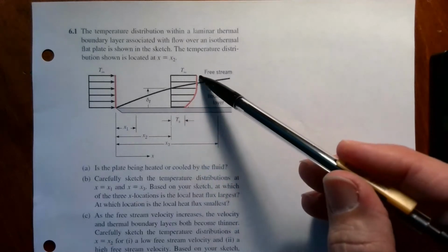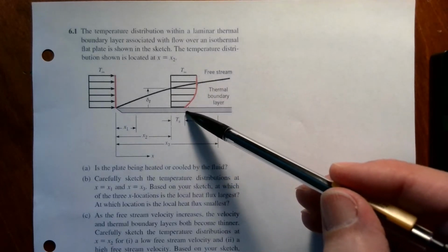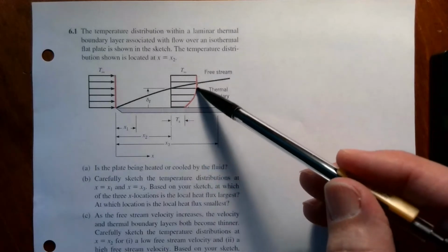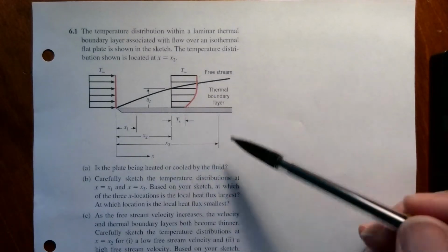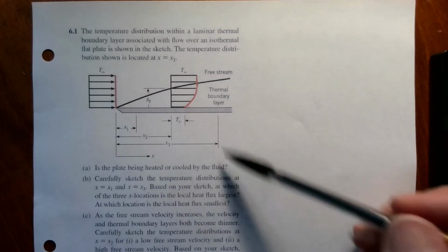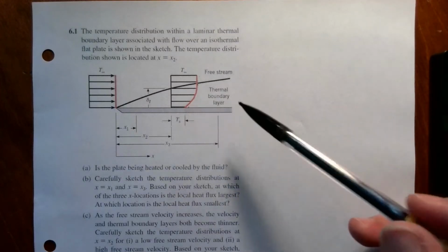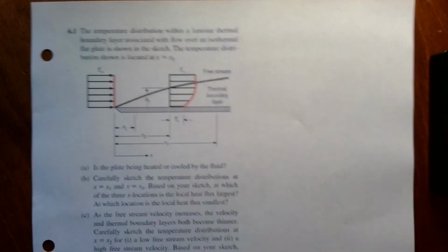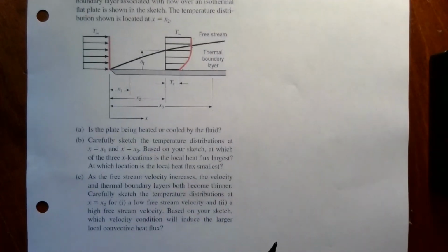And so here you can see T ambient is larger than the temperature of the surface for this particular situation through this profile. So that's the answer to the first question. Is the plate being heated or cooled? Right? In this case, the plate is being heated. Carefully sketch the temperature distribution at